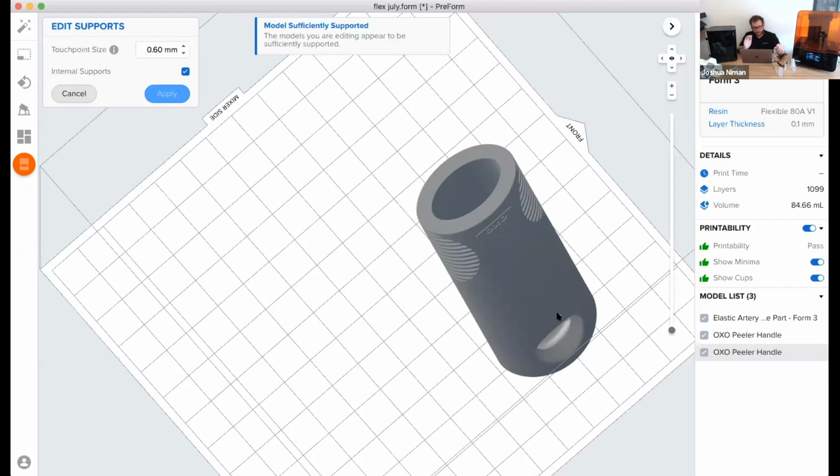So you will not see that dimensional change in the z-axis that you would on a Form 2, where parts would get shorter because they were being compressed. Parts should come out pretty much true to size in the z-axis. But you still may get a little weirdness right at the top because of the laser behavior just being different than the rest of the part. Right. It's going to be a lot more minor, and if you're going to see any dimensional inaccuracy, it's probably more likely to be too long rather than too short, by a much smaller factor than it would be on the Form 2.